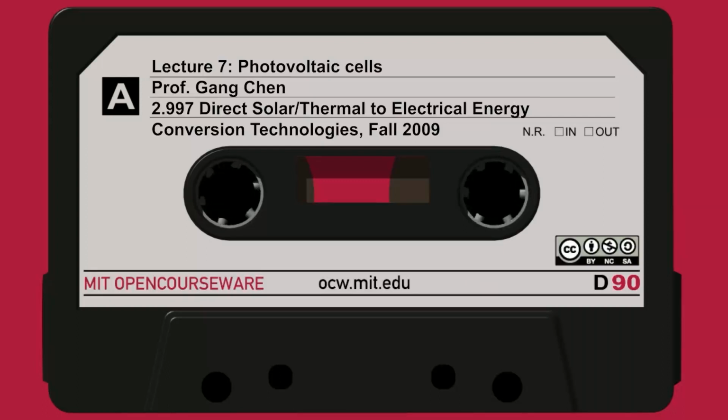Okay, so that's, let's say, the minority carrier device's Achilles heel. And in that sense, I can argue thermoelectrics is good because it's a majority carrier device and doesn't have a severe recombination problem. The other problem is absorption. To me, a photon comes in: the first step is absorption, the second step is where the charge goes. So this is really the first step.